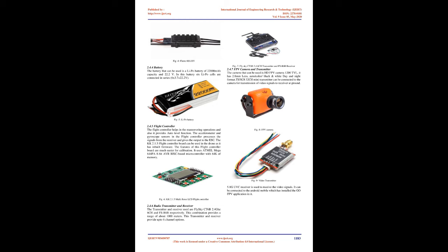2.4.4 Battery. The battery that can be used is a LiPo battery of 22,000 mAh capacity and 22.2 V. In this battery 6 LiPo cells are connected in series, 6 x 3.7 equals 22.2 V.